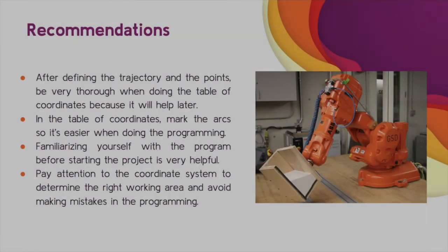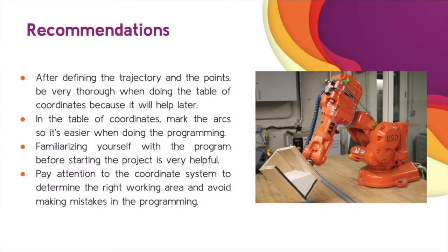These are only some recommendations. The first is that after defining the trajectory and the points, be very thorough when doing the table of coordinates because it will help later. The second one is that in the table of coordinates, mark the arcs so it's easier when doing the programming.